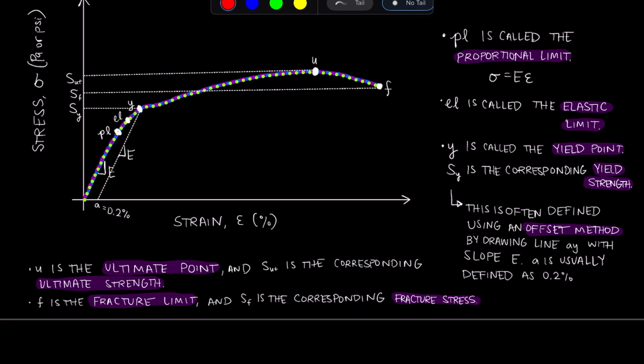So keep that in mind when you're thinking about materials processing, is that you're going to typically affect the yield strength and the ultimate tensile strength, maybe the fracture strength, but you will not affect the Young's modulus much, if at all. All right, now these stress-strain curves that we've been looking at are generated typically from a tensile test. This one that we're looking at here was generated from a tensile test.